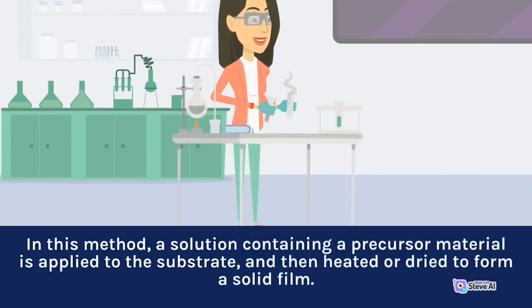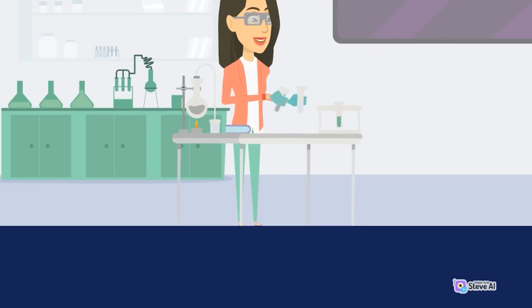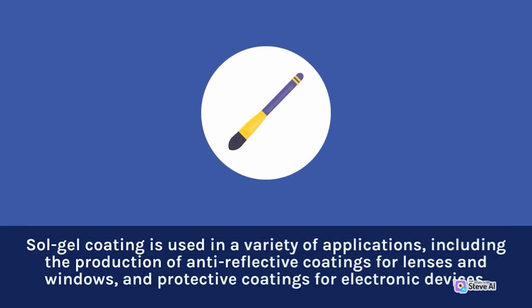In this method, a solution containing a precursor material is applied to the substrate, and then heated or dried to form a solid film. Sol gel coating is used in a variety of applications, including the production of anti-reflective coatings for lenses and windows, and protective coatings for electronic devices.